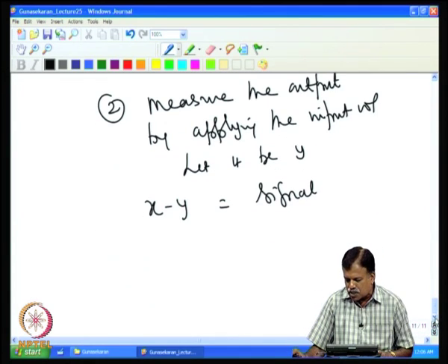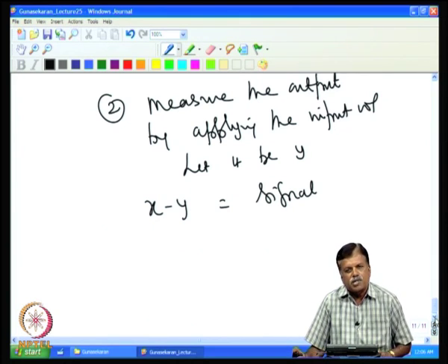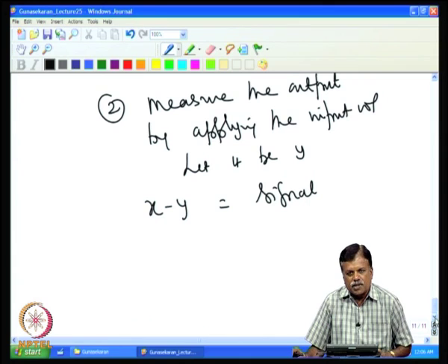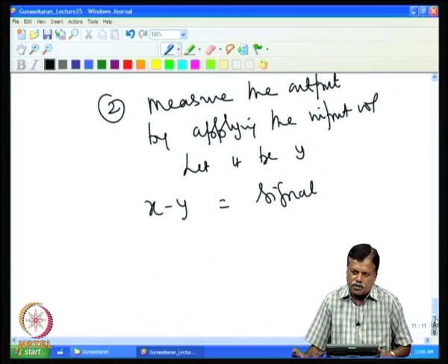So, obviously, one can see that in analog circuits we will be fighting most of the time against this offset voltage drift. This is one of the important problems, or one of the difficult problems to crack in analog circuit design, particularly when you are dealing with a low level DC signal. So, one has to be aware of how to calculate this offset voltage drift.